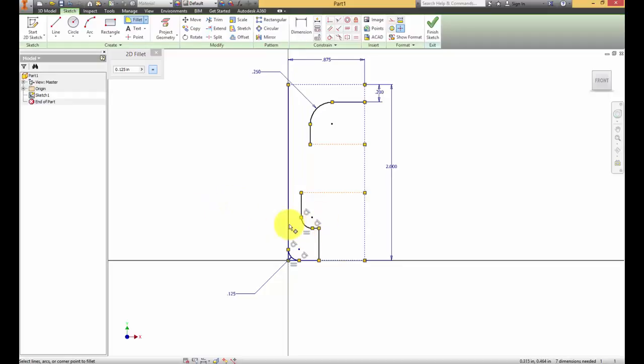And then the next thing that I know for a fact, I'm going to drag this over some, and I want to fillet, but my fillet changes to 0.08. I want to fillet this right here and this one right here. So those are where I've got lines and not arcs. This one and this one will have arcs. So I'm going to put those on there in a few moments. Show you another way that may help some people.